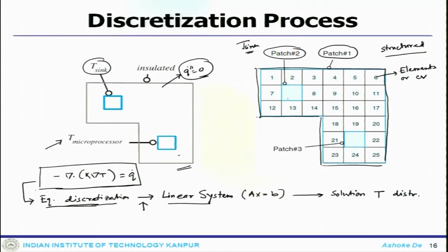The boundary conditions that we have discussed so far, at least a couple of them, you can see the direct application in this particular problem. One is the Dirichlet kind of boundary condition, which is applicable to patch 2 and patch 3. Patch 3 is the heat source, so that will have a high temperature. This is the source. So, it could have a high temperature, or patch 2, which is always the heat sink, will have a low temperature.